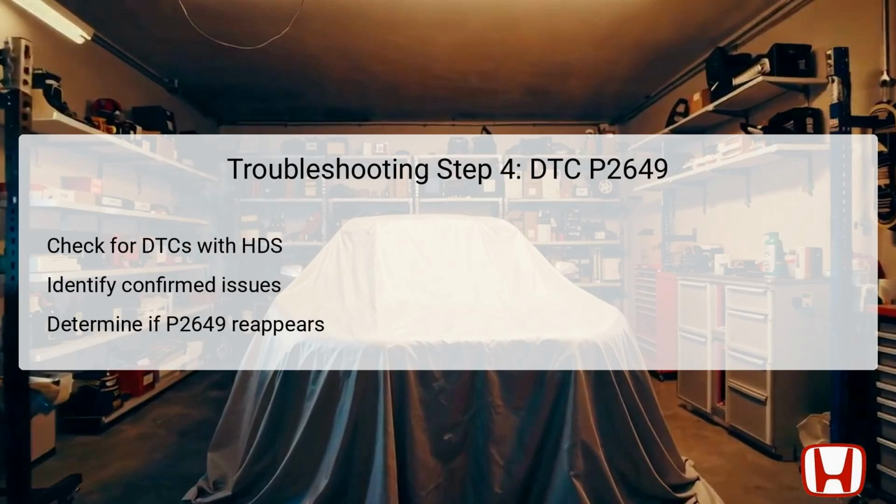Following the idle phase, the next step involves checking for pending or confirmed DTCs using the Honda Diagnostic System, HDS. This check is crucial in determining whether DTC P2649 is still present after the engine has been run under test conditions.